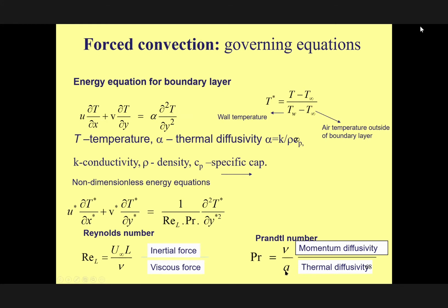This depends on the conductivity and on the viscosity, and it shows which one is dominating. For example, for a liquid metal, because the conductivity is very high, the Prandtl number is less than 0.1. For air it is around 1 or 2. That represents the physical phenomena of the motion.